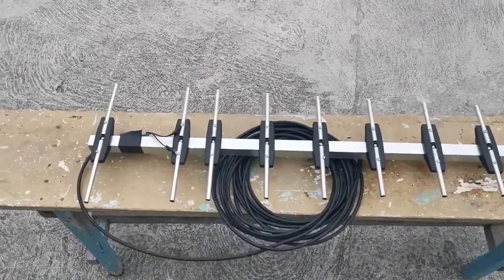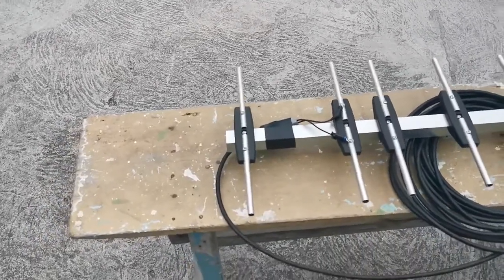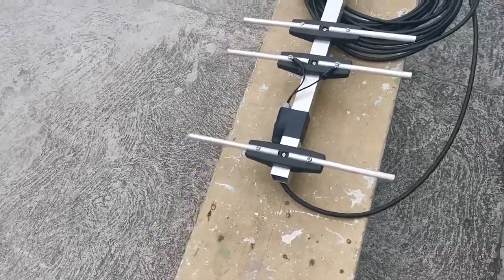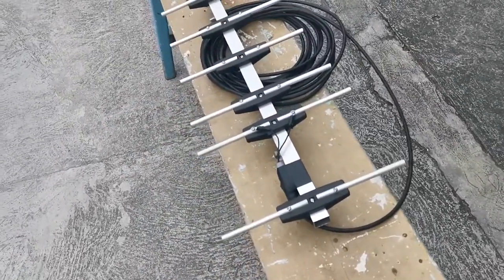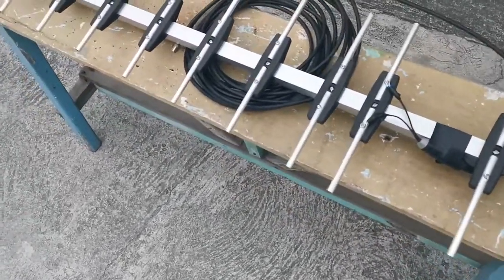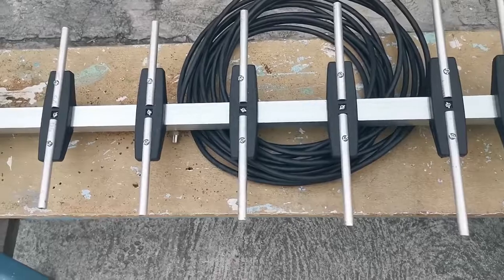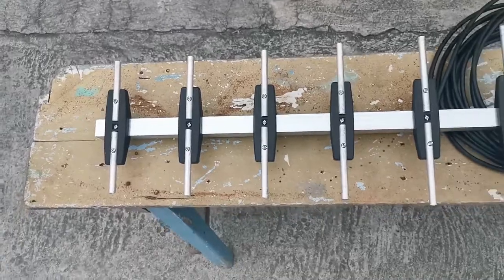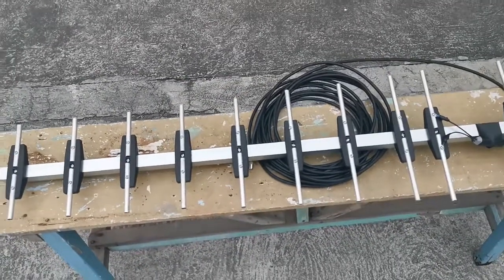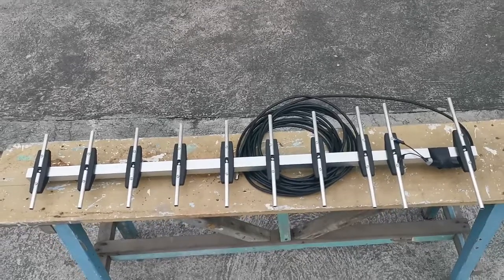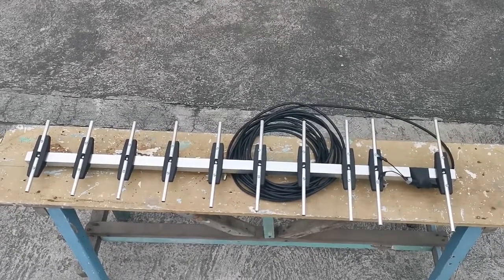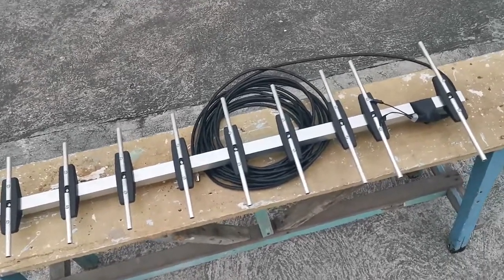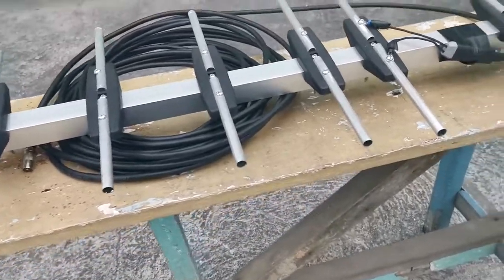Typically, a reflector produces 4 to 5 decibels of gain itself. This is because the radiation is doubled since it bounces back into the dipole. Then, each director added provides roughly 1 decibel of gain. The formula for calculating the gain of Yagi Uda is G equals 1.66 multiplied by N, where N is the added elements. Therefore, the gain for this Yagi Uda antenna results in 14.94 decibels.